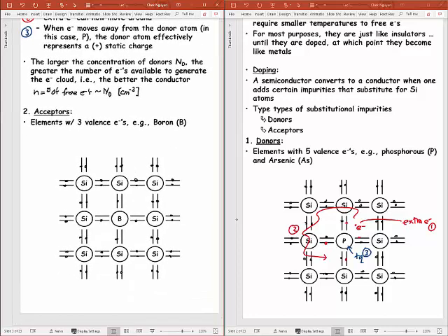And so if we go ahead and do the same thing, you can look down here. I'm now substituting for silicon a boron atom. And so that boron atom, it actually will give me 3 electrons. So there's 1, there's 2, there's 3. 3 nice electrons in there.